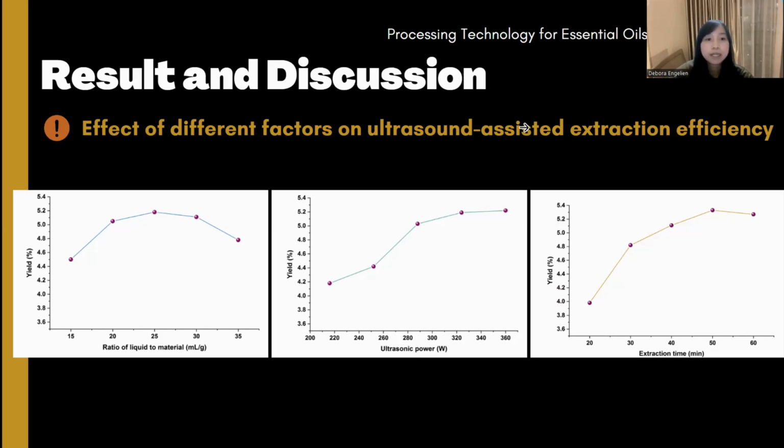The yield of GBLPS increases faster with the increase of the liquid to material ratio at lower liquid to material ratios. This may be explained by the increase in solvent ratio resulting in higher osmotic pressure of the cells, thus accelerating the efflux of intracellular material. On the other hand, the increase of solvent volume led to a larger area of ultrasonic action, which results in greater ultrasonic efficiency.